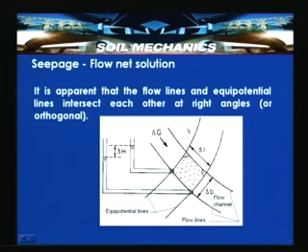Similarly, if I take an equipotential line, that is if I tap and measure the total head here, what we get is also the same total head, which indicates that total head is constant along this. But if you come down here, because the flow is taking place, the energy is transferred in the form of a frictional drag to the soil grains. So, when the flow is taking place through soil, the head loss has to occur.